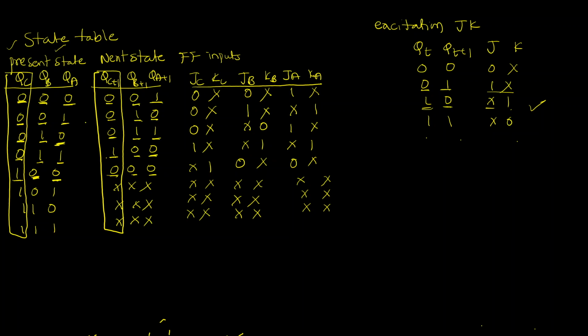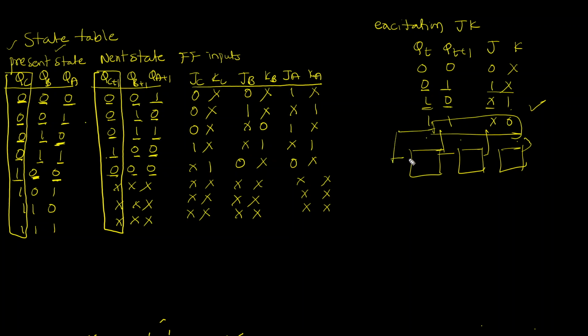So what I try to do is, I have a couple of flip-flops. From these flip-flops, I take the present values, give them to some circuit, and from there I get some values. Those I give as inputs to the flip-flops. Are you getting? So the present state is input, and the output after processing the present states is input to the flip-flops, right?